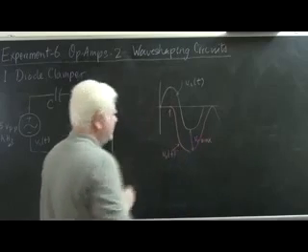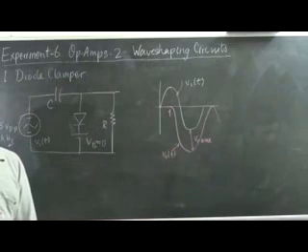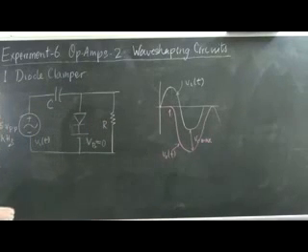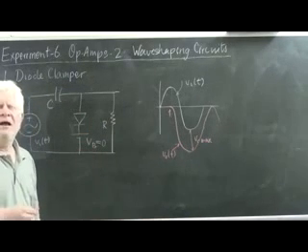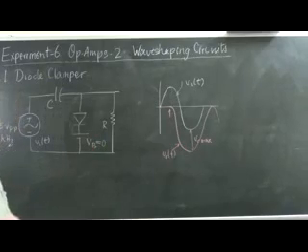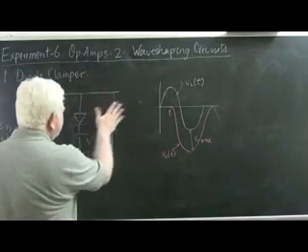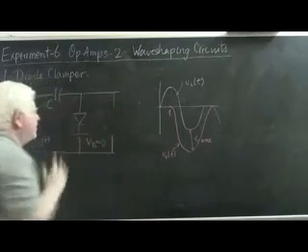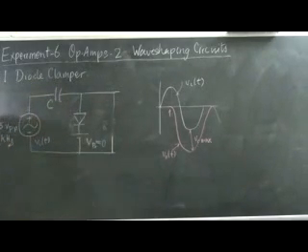Now, we really haven't spoken of the resistor, and honestly, as far as the argument up to this point is concerned, let us pretend in fact that the resistor is absent. Now, if the resistor is absent, the capacitor once charged, and assuming that there are no other leakages, will stay charged forever.